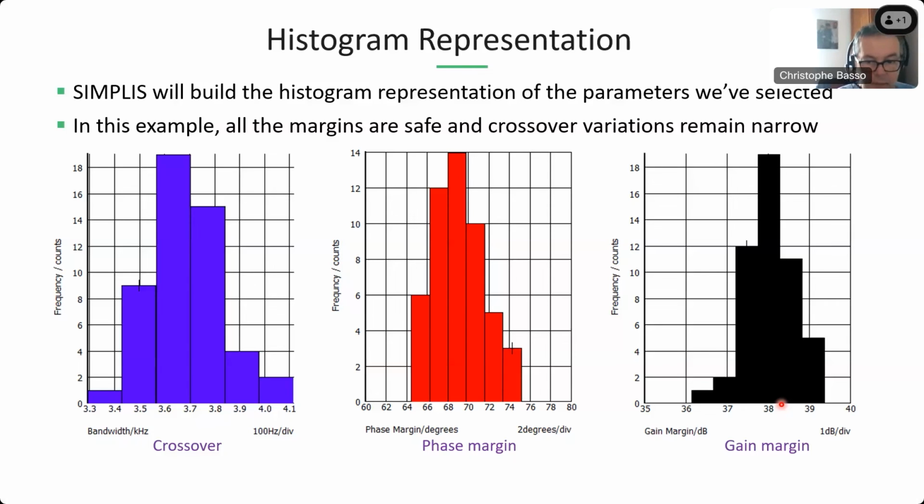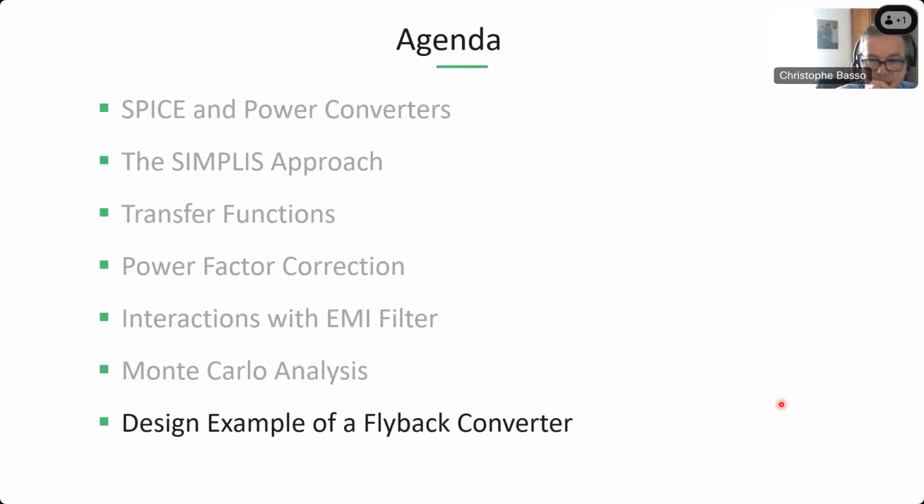Can you tell me that this new capacitor is going to be safely included in the new bill of materials? Well, if you run this type of analysis and you know the ESR boundaries between which the power supply is stable, then you can safely accept or discard the proposal of replacing the capacitor.